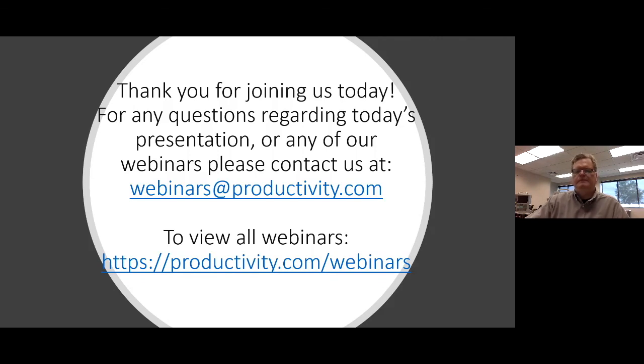Dave, does the next gen control no longer need G103 P1 to limit block look ahead? As far as I know, we still need to use that. If you are witnessing that maybe you don't need it, then that's new for me. This question came up before you mentioned G103, Dave. I think that's where it comes from. Oh, okay. Thanks, Bill.